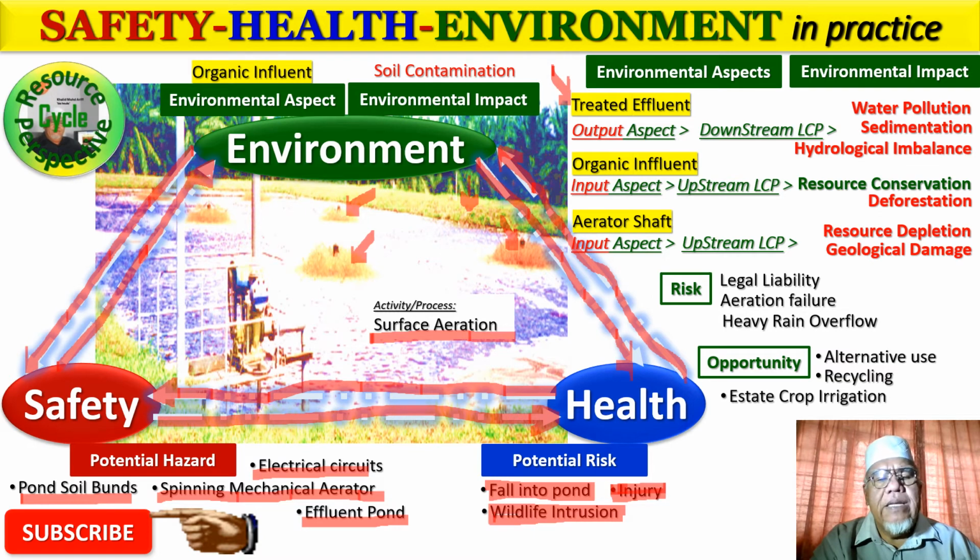If it is slightly deeper, then we have to use mechanical aids, like these mechanical aeration techniques, to ensure good exchange or good intake of air into the water body to enhance the content of dissolved oxygen, to enhance the microbial growth of aerobic bacteria, which would decompose or use up all the organics in the water and convert them into carbon dioxide and water.